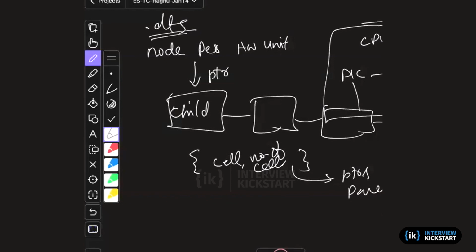But once the blob is created, it is flattened so that it is easy to manipulate. The DTB can be flattened by the parser afterwards, or it can be flattened earlier also. So the input is in a tree structure, reflecting the hardware hierarchy, and the binary version is a flattened thing. Basically, it can be directly manipulated without having to traverse all this. So that's basically all I know about device tree.